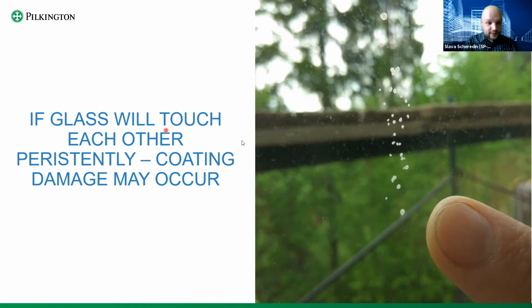The question from Tina: is there a suggestion or norm of how to install dark colored curtain rolls to the large glass facade to avoid thermal stress? The best way: temper everything and you don't have to worry about thermal stress at all. So tempered glass, way to go solution. With tempered glass, you can use whatever you like. No thermal shock, never.